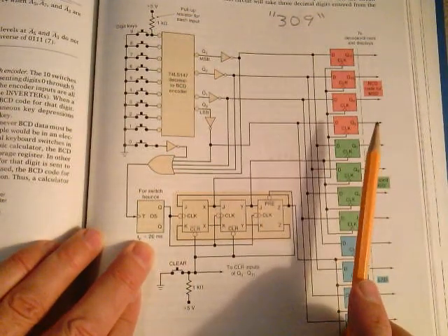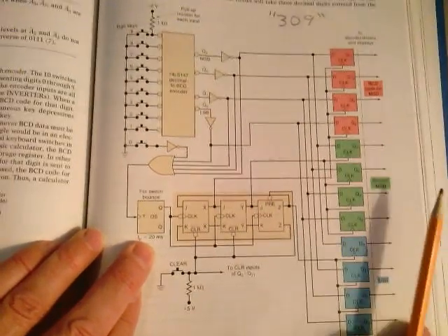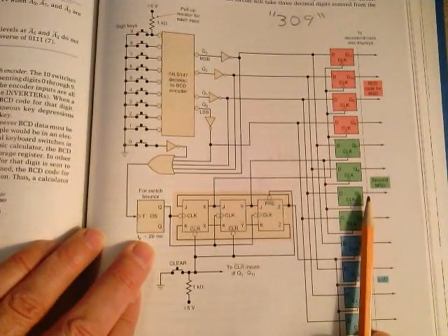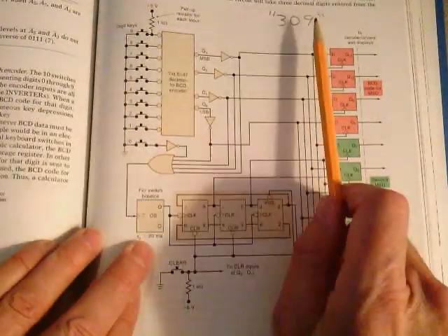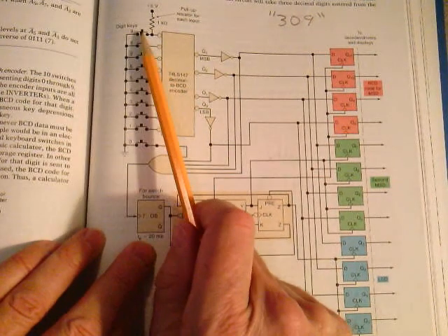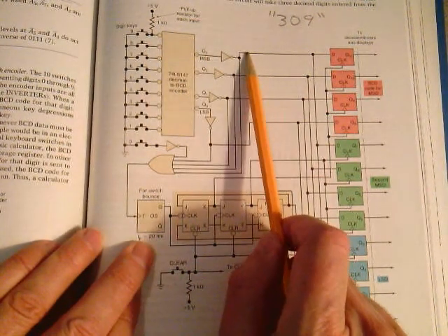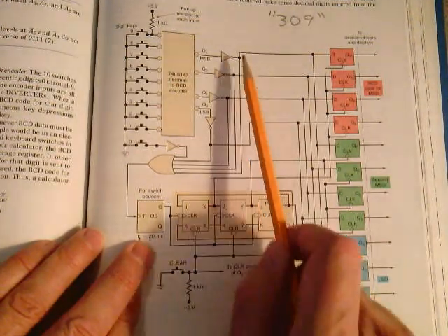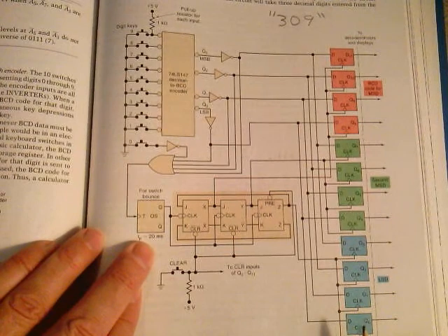It lights up through your BCD to 7-segment design. You have your 0 here. It lights up on your 7-segment display through your BCD to 7-segment display. And now you push a 9. We push this 9 right here. This goes low. Let's look at the outputs out here. 1, 0, 1, 0. There's your 9 that gets set up. It gets set up here, it gets set up here, and it gets set up here.